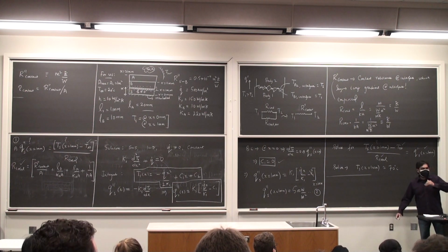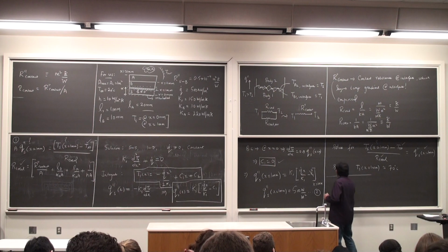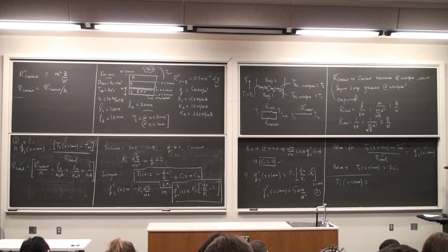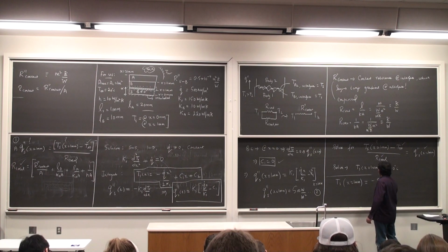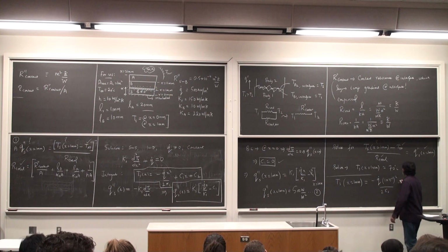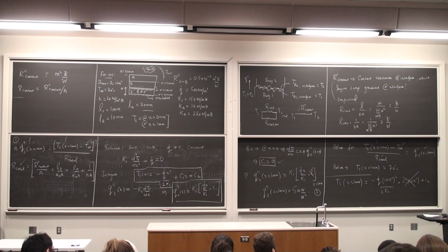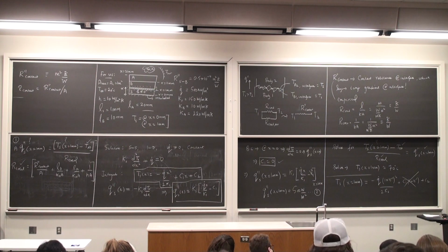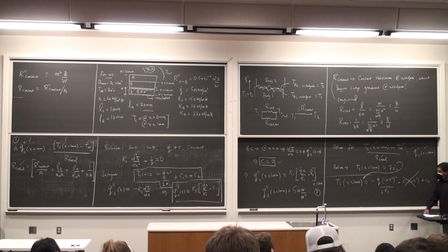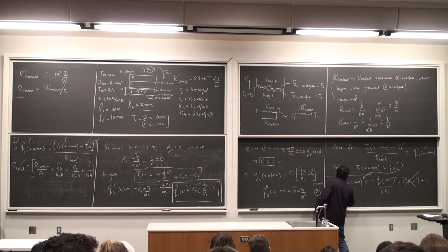Moving on, right? I need to find the temperature at the bottom surface, which is now fairly trivial because I know the temperature here. I can find out the constant C2. So Ts at x is equal to 1 millimeter, I go back to my quadratic profile which has been obtained there. So this is minus q dot times 1 times 10 to the power minus 3 squared, over 2 times Ks, plus C1 times x, plus C2, but C1 is 0. We just calculated, right? Ts is known to me. Substitute. q dot is known to me. C2 can be calculated.